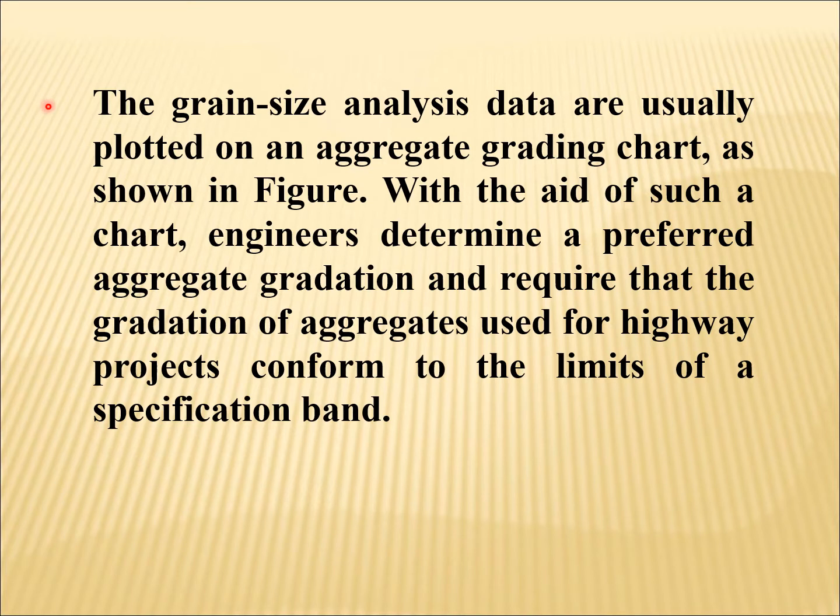The grain size analysis data are usually plotted on an aggregate grading chart, as shown in the figure on the next slide. With the aid of such a chart, engineers determine a preferred aggregate gradation and require that the gradation of aggregate used for highway projects conform to the limits of a specification band.